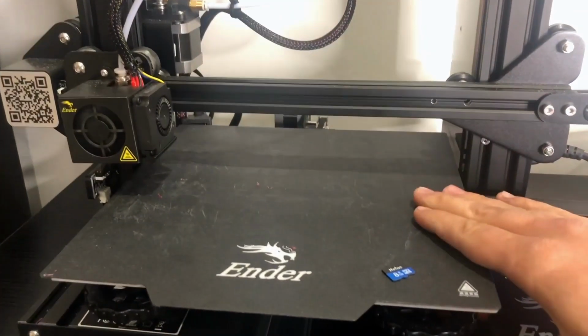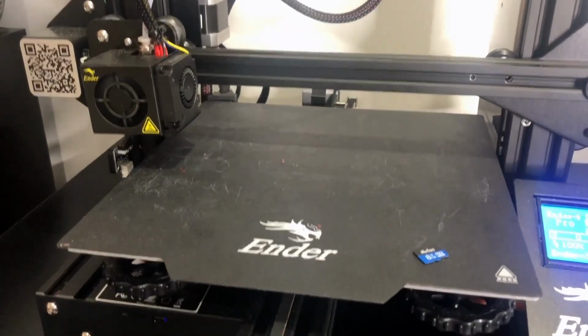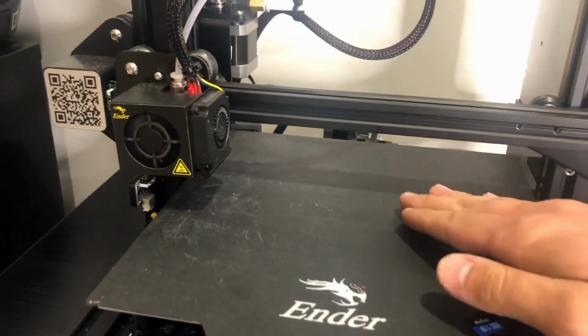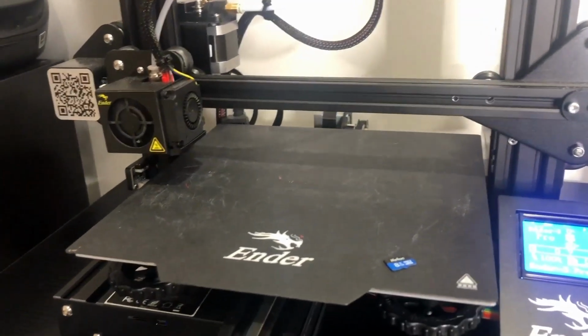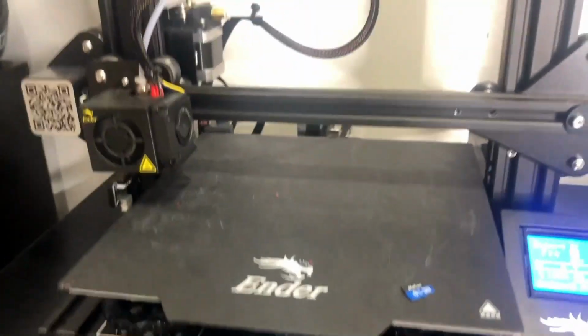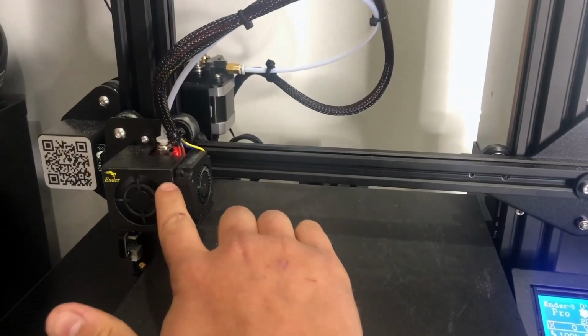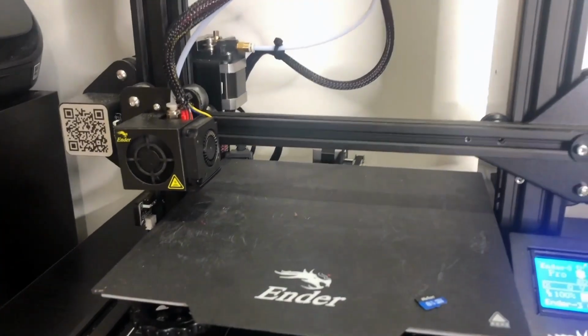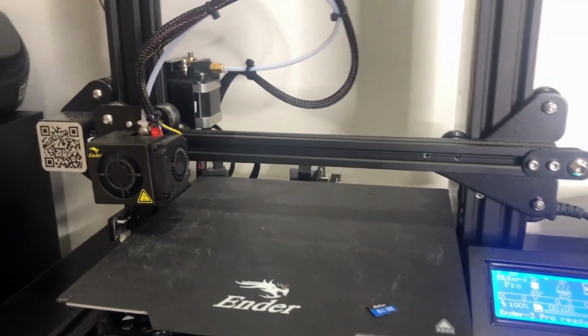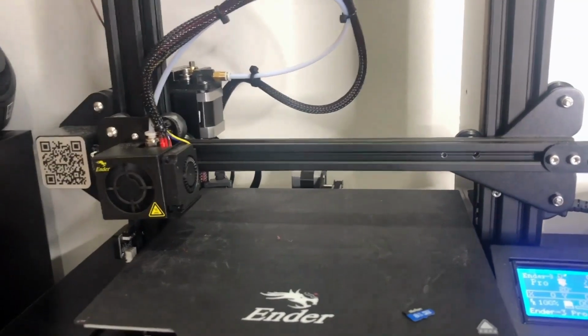So this is our printer bed. This is where our filament will be extruded onto. It'll begin with one layer and then a next layer and so on and so forth. As mentioned, it will be in 0.2 millimeter increments. So this is our extruder head that will move up this axis, which is our Z axis, in 0.2 millimeter increments. We can adjust that, but as we said before, this will be a 0.2 millimeter layer height print.